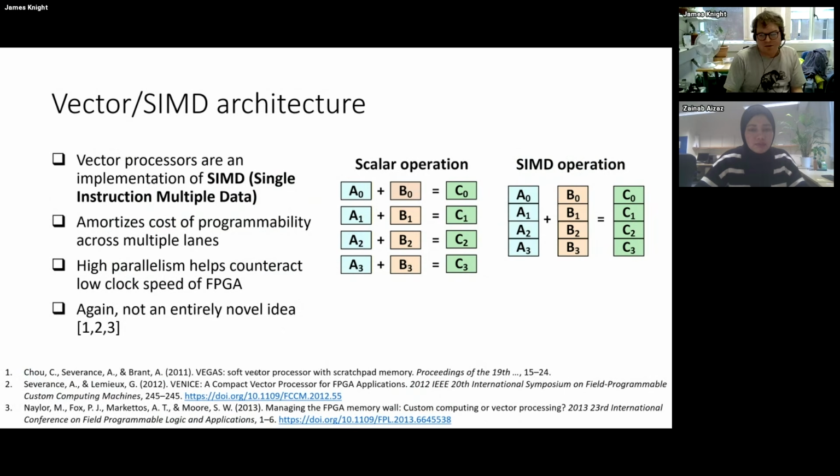As I'm sure all of you know, in a SIMD system, your operations look much like normal operations in a RISC CPU. You might have an add operation that reads two vector operands and writes back the sum to a destination register. A SIMD version would be exactly the same, but the registers would be much wider, and you'd be adding together multiple values at once.